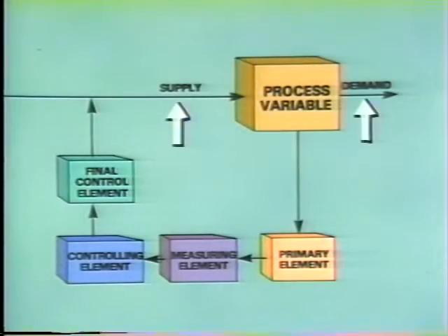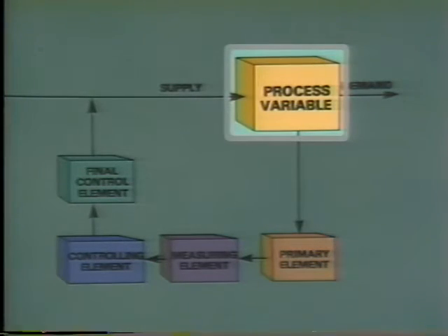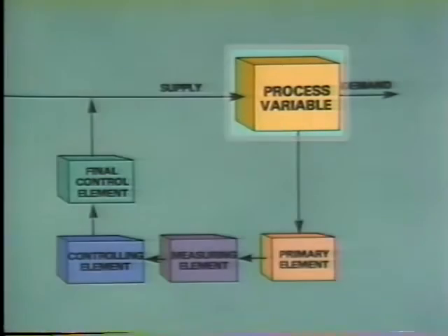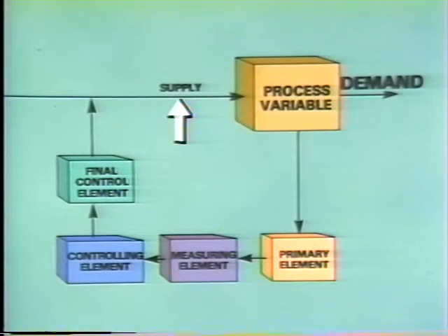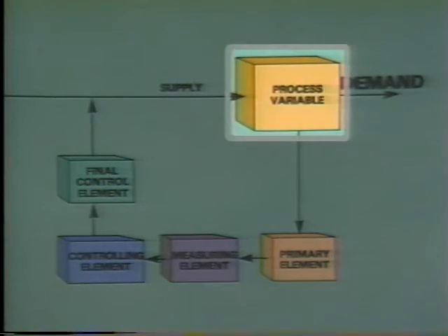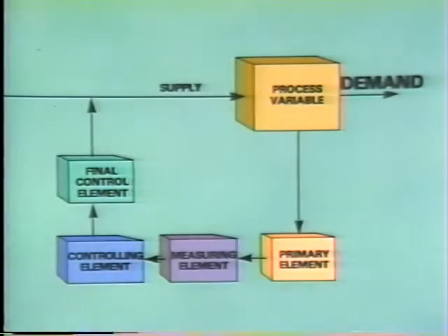As long as the supply and the demand are equal, the process variable should not change. But if the demand changes and the supply doesn't, the process variable will change. Well, let's see how the feedback control system would respond to this change.